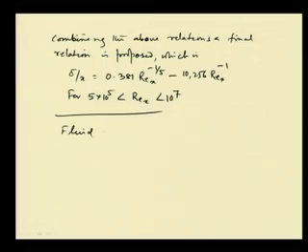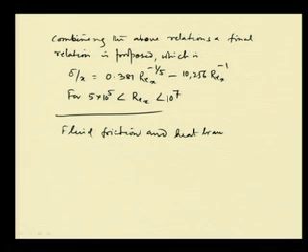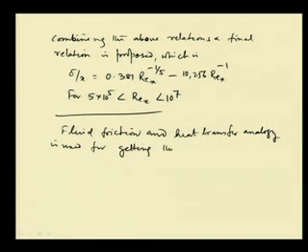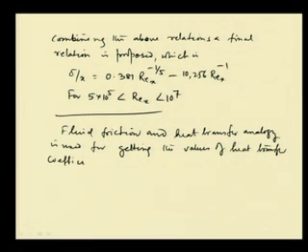But as I discussed earlier also, for turbulent flow situation, it is usually the analogy, the fluid friction and heat transfer analogy, that is used for getting the values of heat transfer coefficient, because that mechanism of transport is not very well understood in case of turbulent flow situations, and the theoretical development is really a difficult job.